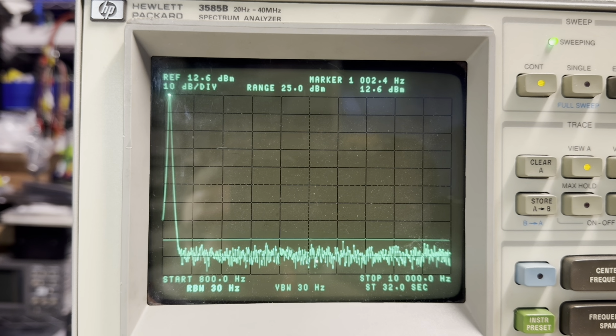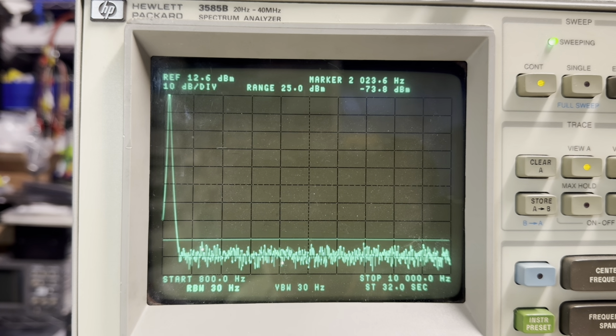And that's what we did in the previous video with the notch filter: we used that notch filter to remove the fundamental, and then we could focus in on the lower signal levels of the harmonics. And that's what a distortion analyzer does. A distortion analyzer is going to remove this large fundamental signal so that it can zoom in and really find these low-level harmonic components and the noise. So let's look at this now on the distortion measurement set.